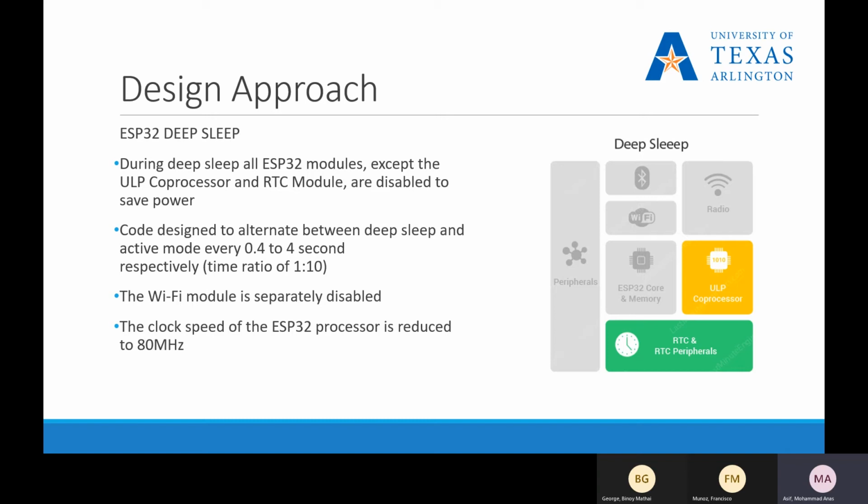Additionally, it is possible to individually code what peripherals need to be shut down or kept on before entering deep sleep mode. However, by default, ESP32 automatically powers down the peripherals not needed by the wake-up source. All of this is very useful in our application.